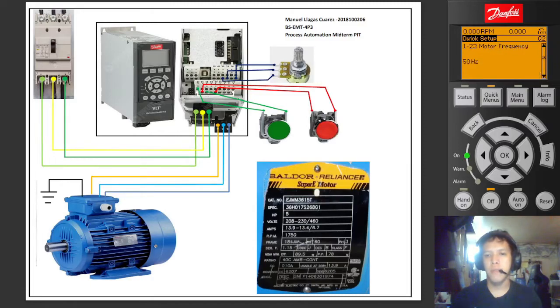Now we're going to go to motor frequency. In our motor nameplate, the frequency is 60 Hertz, so we're going to set it to 60 Hertz, and press OK.